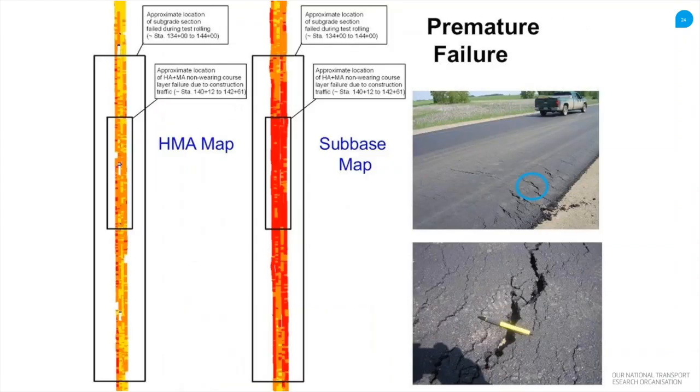So what happened on the second day of the paving is we noticed an asphalt truck had been paving on the northbound side. When it drove off on the southbound side, you can see here, it tore off the asphalt that had been paved the day before. So that premature failure is only 1 day old. You can see my pen on the enlarged area, showing that the asphalt stiffness was just not enough, the compaction had not been done properly, and they just tore it off.